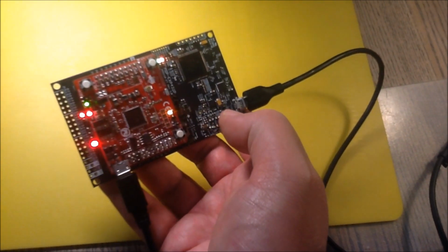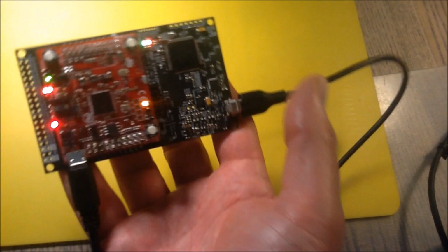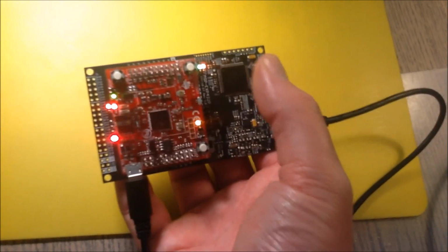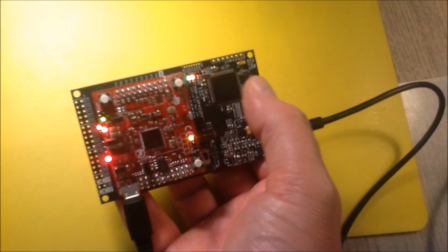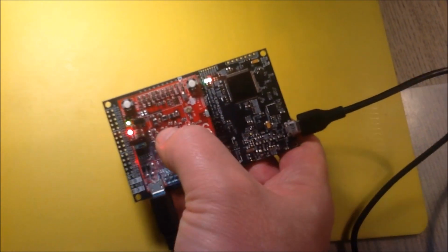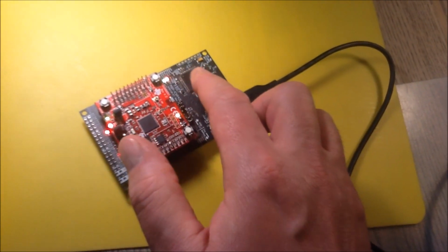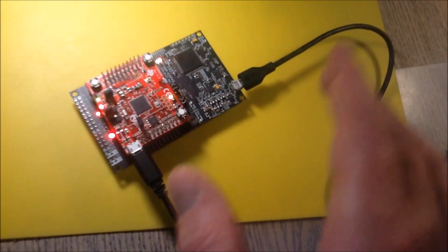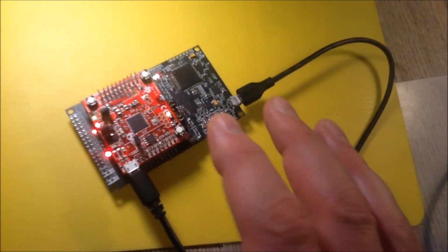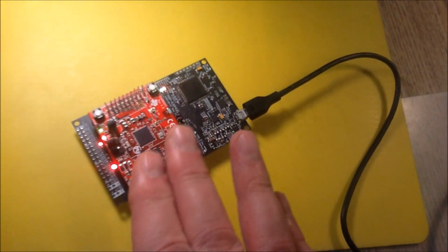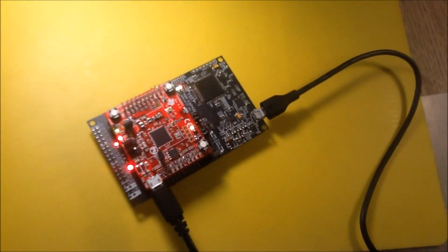The MSP432 is now ready to run your projects. It has an RTOS running that's well configured. It can connect to your access point via the SimpleLink board that we're using here. And you can now either listen to sensors and send the information to servers using the Wi-Fi board, or you can collect information from websites and use that in your application.